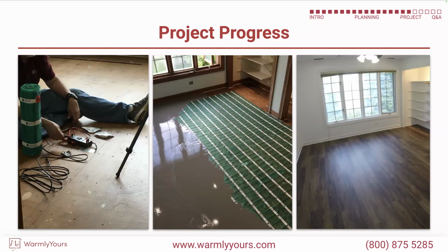So here we can also see in the middle that the self-leveling cement is about halfway installed. That's just showing you how you're going to be carefully walking across that, pouring that down, and evenly coating that whole subfloor to embed that system about a half inch deep. That's what's going on in that picture, and then your final picture is your finished room. Yep, we've got the same flooring all the way across in the closet, but there's no heat over here, but there's self-leveling over here.